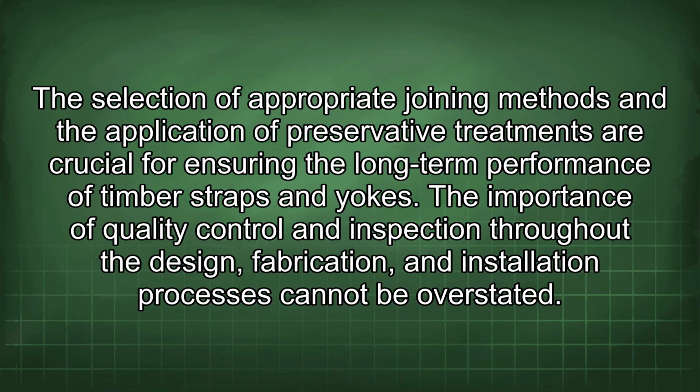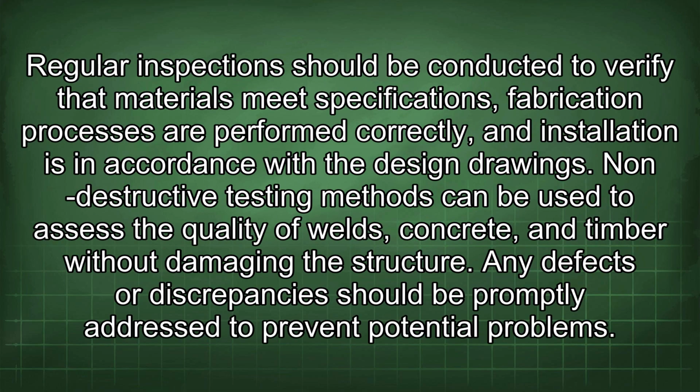The importance of quality control and inspection throughout the design, fabrication, and installation processes cannot be overstated. Regular inspection should be conducted to verify that materials meet specifications, fabrication processes are performed correctly, and installation is in accordance with the design drawings. Non-destructive testing methods can be used to assess the quality of welds, concrete, and timber without damaging the structure. Any defects or discrepancies should be promptly addressed to prevent potential problems.